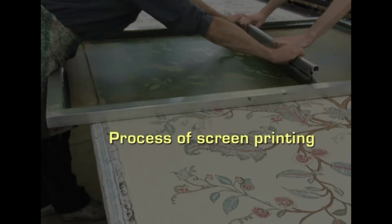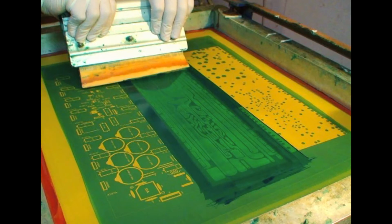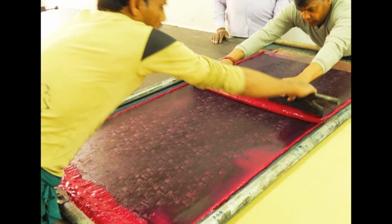Coming to the process of screen printing, in printing, the fabric is spread flat on a padded table and fastened securely in position. A screen representing one color of the design is set by hand over the fabric in the first position, with metal brackets on the side of the table to hold it in place. The dye is placed at the edge of the frame and a rubber knife or squeegee moves the dye across the screen and forces the color onto the fabric through the design. This is repeated as many times as necessary to print the fabric completely. This process must be repeated for each color to be used in the design.